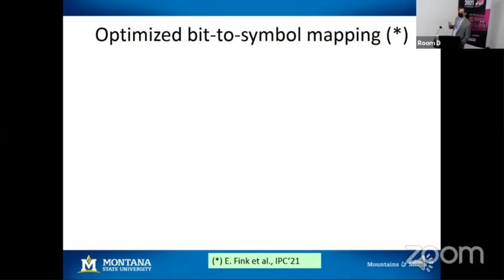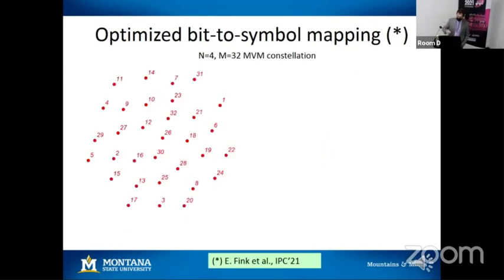Okay, now how are we going to do bit to symbol mapping? Gray coding is impossible. Let's see why. Let's take an example. Again, the 2-core multi-core fiber, 4 spatial degrees of freedom, 32 points. Actually, for this particular constellation, there are published results by other groups because obviously this problem is interesting in quantum mechanics as well. In order to show you how the constellation looks, I will make a graph. Since we cannot visualize the hyper Stokes space, here are the 32 points.